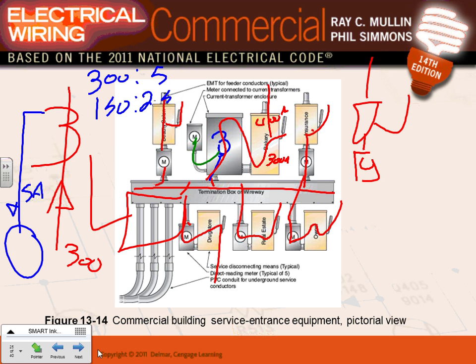So if the owner says you have to add that in, and it makes you need more than 200 amps, that's when they're going to ask you, well, I have a new tenant here, can you solve the problem for us? That's when you show your interest and knowledge in the code. He said, well, you can't, guys. You have to have a main here. And you know how much it costs to cut through this gutter and put a main here? It's going to cost you, but it's doable. Everything is doable. We are in the business of providing solutions to the customers. So you can't just cut these conduits here and land them in a main disconnect here, and then continue.